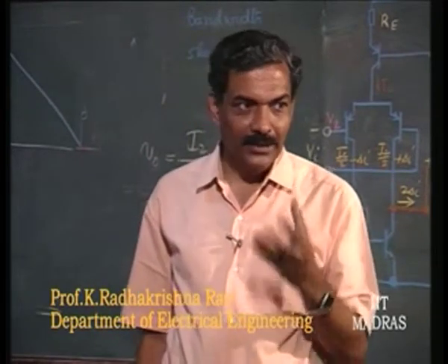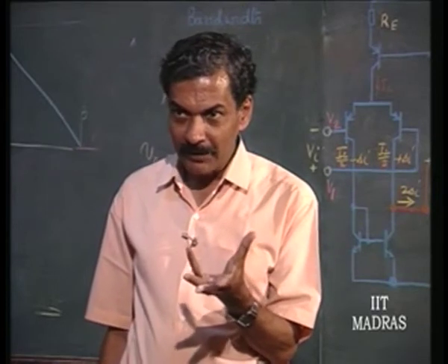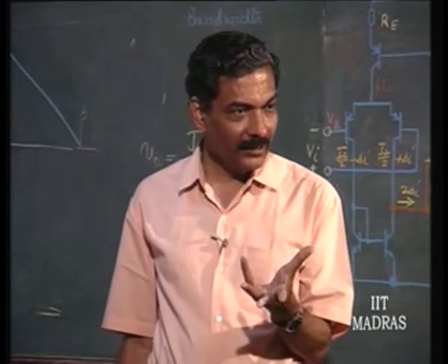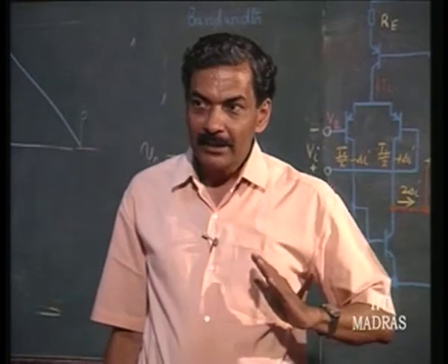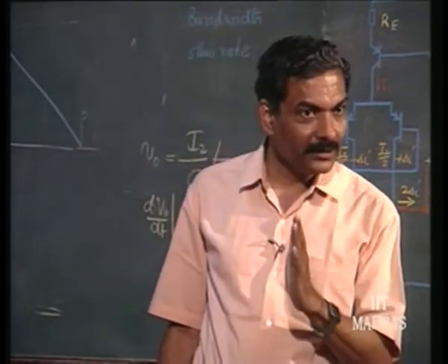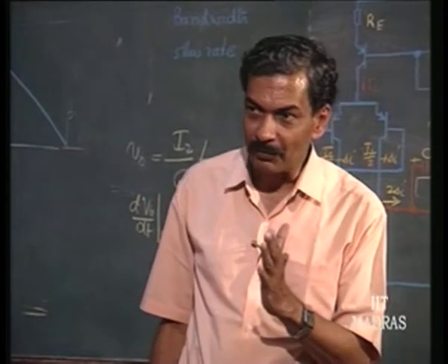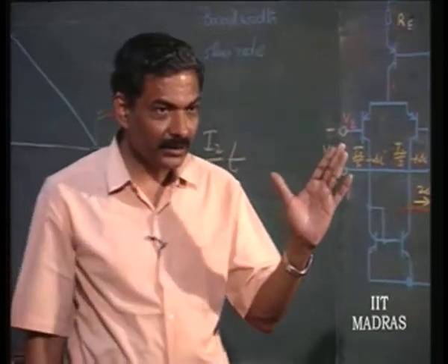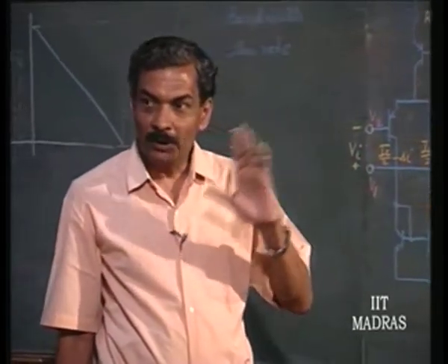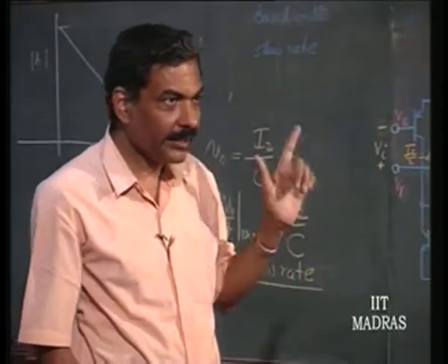So, you will see that if you are expecting a sinusoidal output at the output of the op amp, and if you are demanding higher rate than the slew rate, the sine wave starts getting distorted, gradually transforms itself at around 0 into a triangular waveform, unlike other distortions which are mostly signal level dependent distortions. This is rate dependent distortion.